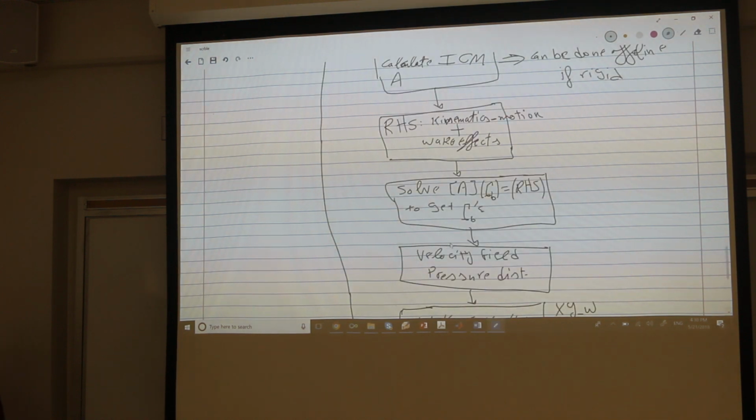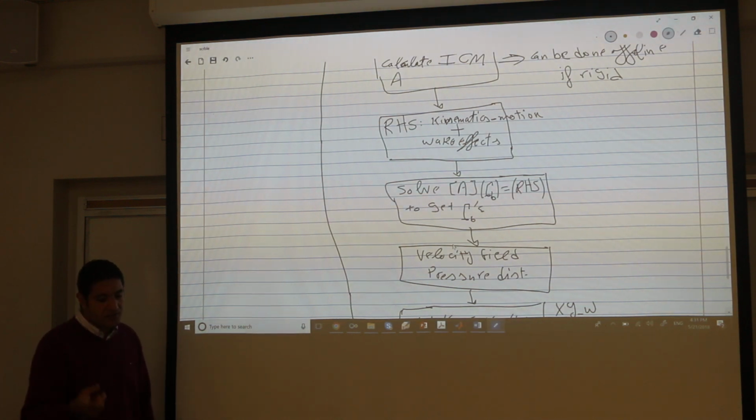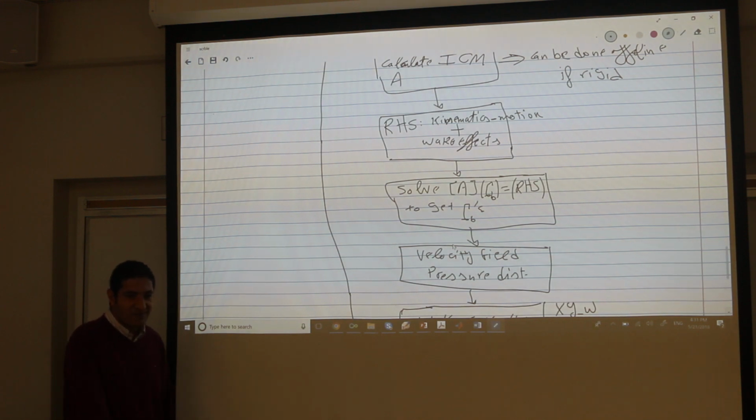Yes, please. Is this basically CFD? No, see, if you want to say CFD, it stands for computational fluid dynamics, right? So from this definition, yes, it's computational fluid dynamics. But the convention, the norm is that this is too trivial to be called CFD. I'll say this is numerical methods applied to fluid mechanics, aerodynamics, but it's not CFD. If you're solving at least the Euler equation, I would say, okay, CFD. Euler, Navier-Stokes. If we're solving this potential flow, Laplace squared phi equals 0, yes, we can solve it by CFD methods, like